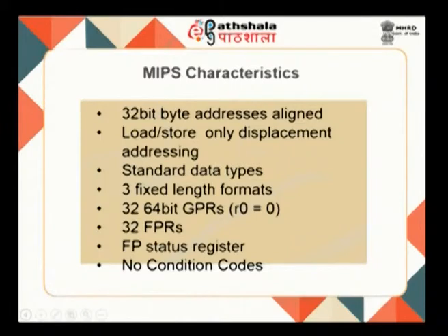The basic characteristic of the MIPS architecture is that it is basically a RISC architecture. It follows a load store ISA, which is a register ISA. It is called a register ISA because the instructions operate only on register operands. I can have an instruction like add R1, R2, R3. So, all arithmetic logical operations will have to be done only on registers, and in order to bring information from memory or write information onto memory, you have what are called load and store instructions. So, load and store are the only instructions which allow you to have memory operands.